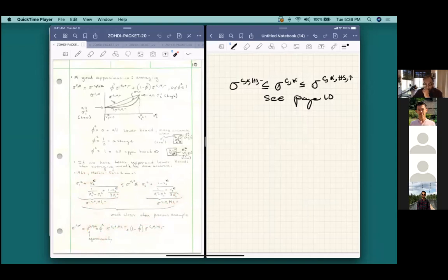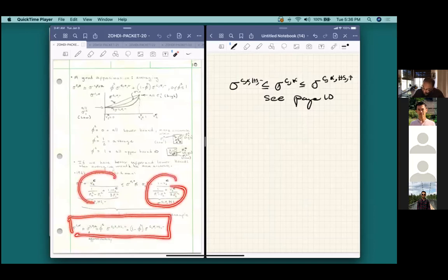That's pretty much the state of the art in terms of what people do, unless they're going to go through a much more intensive computational experimental analysis. So day in and day out, you'll find people at Apple or Siemens or Bosch, or any of the companies that are dealing with pretty complex materials. This is pretty much what they're going to be using. They're going to take the upper and lower bounds, combine them with 1 minus phi and phi, and produce some kind of value for the estimate.